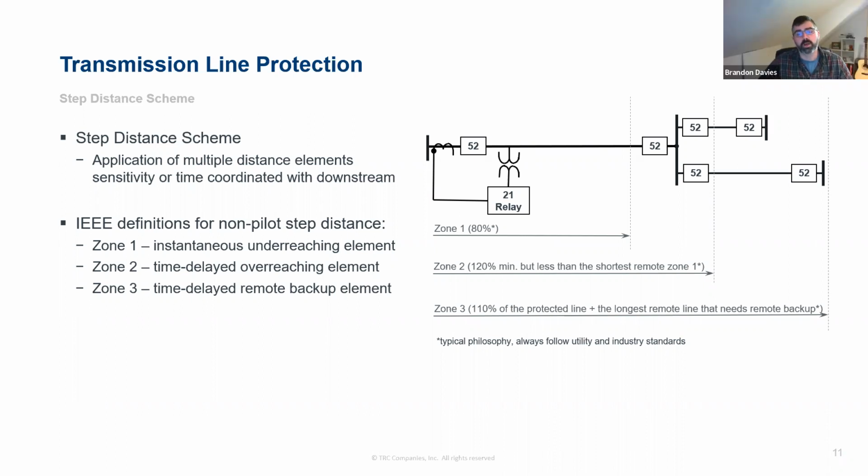Yeah, so in general, the distance scheme where you're measuring voltage and current and turning it into impedance, even if you have a voltage rise on that other phase, the impedance measured, and how the relay looks at that is going to, I guess, cancel that out. You've got a higher voltage, but you're not having as much fault current on that phase either.